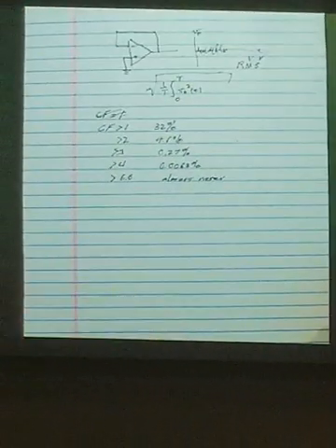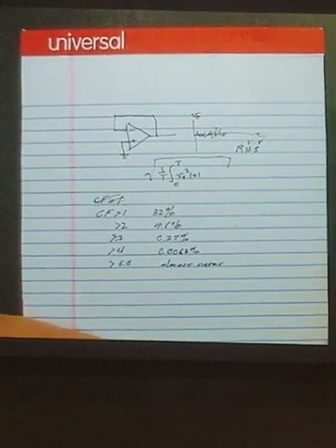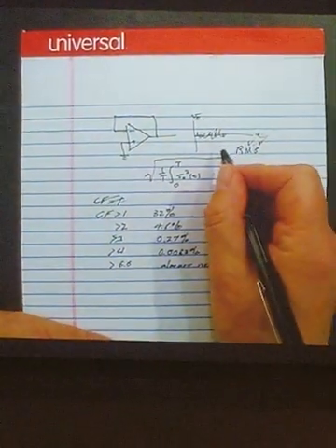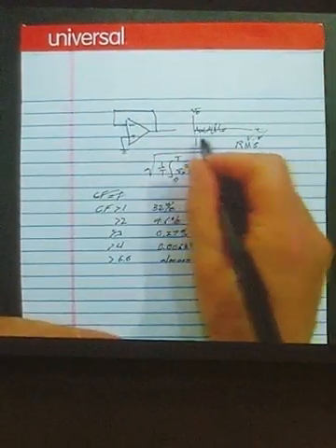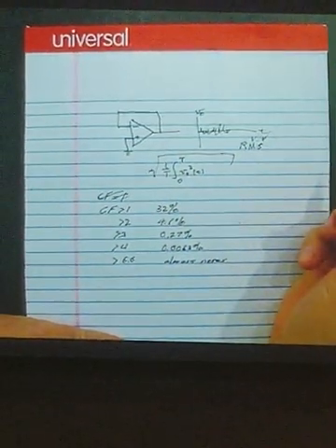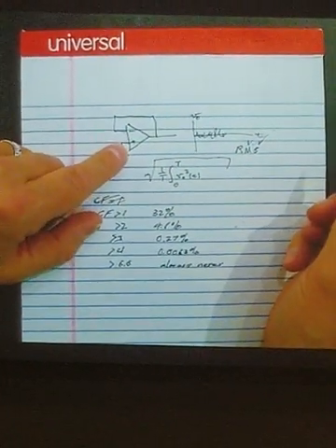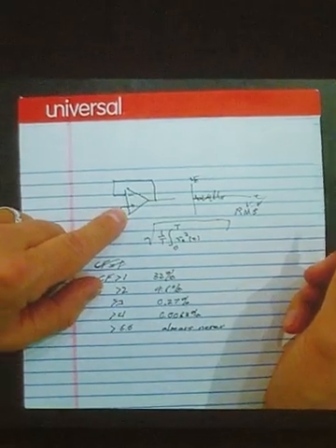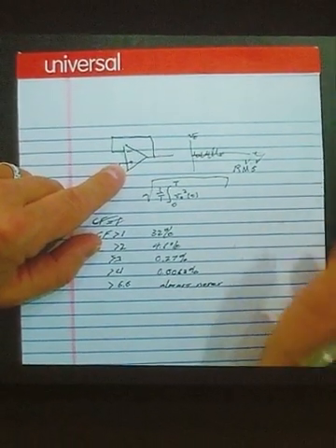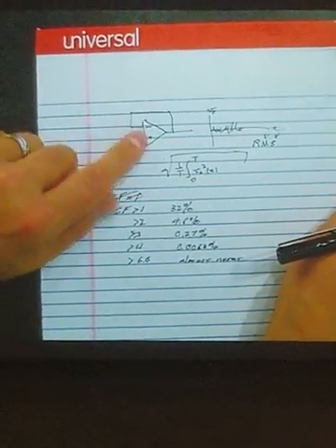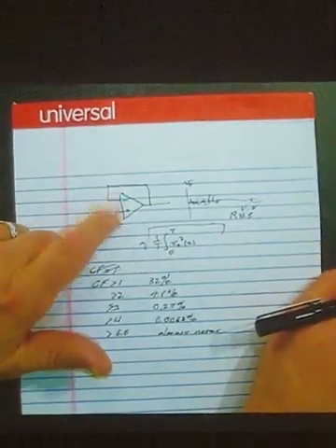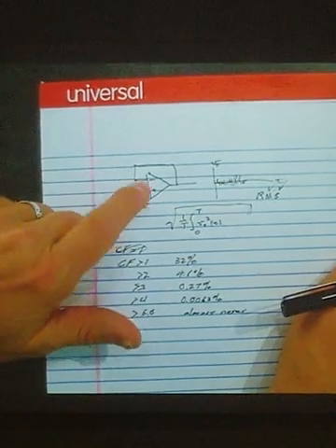Okay, so that's physical noise, and you're actually going to be dealing with a time-dependent signal like that going in. Now, we're setting your amplifier up with a higher gain, which means it has much lower bandwidth. Remember, this is your device under test. This is not your measuring circuit. This is what you hook to it.